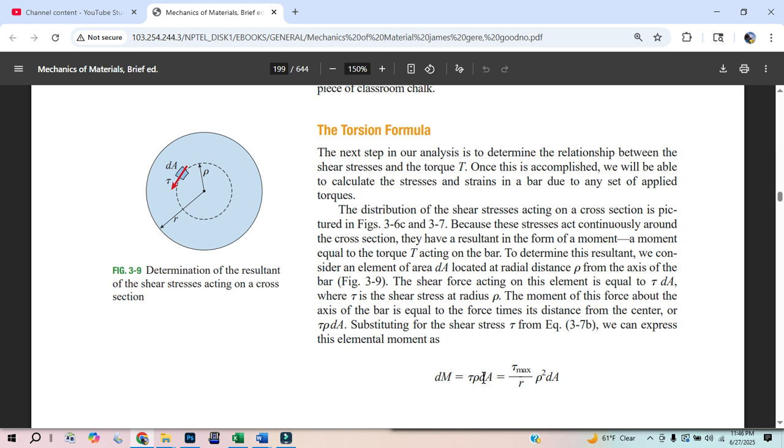So we pick up another rho, so we would have tau rho squared d rho d theta. And we would just integrate rho from 0 to r. That's easy. That just gives us an r. No, I'm sorry, because we already have rho squared, so when we integrate, you have to account for that. For d theta, we don't have any other theta term, so we'll just have a 2 pi.